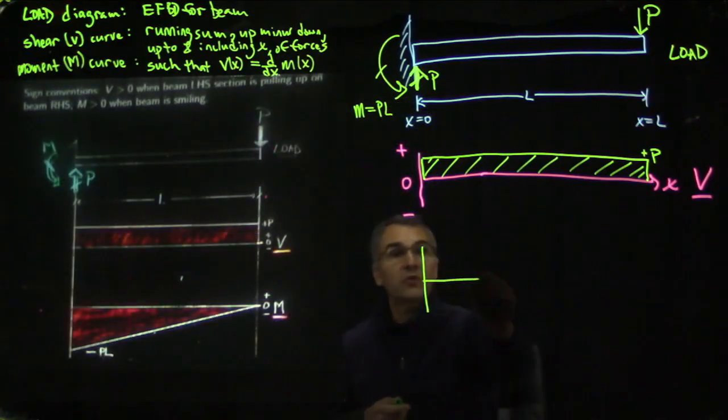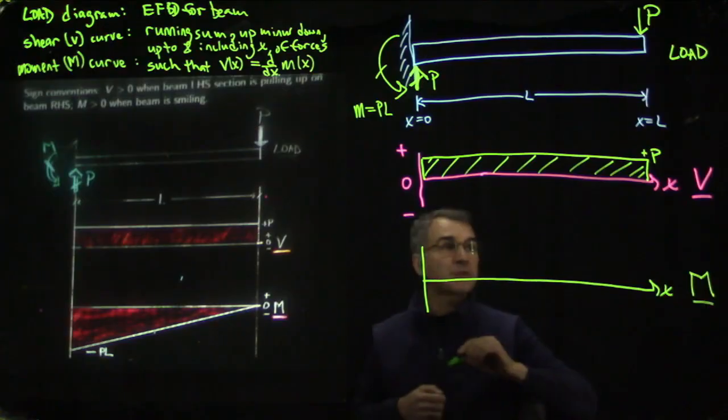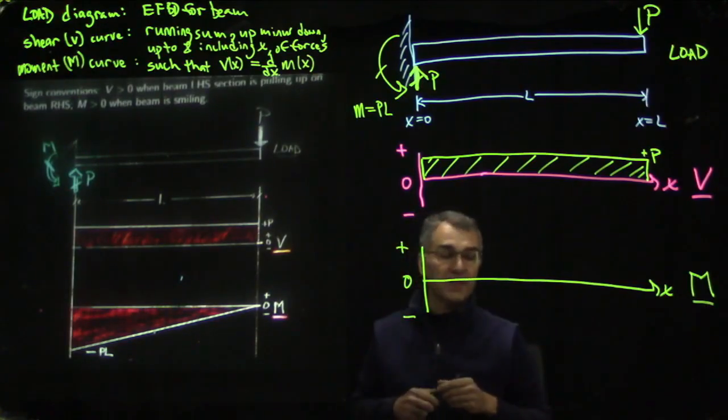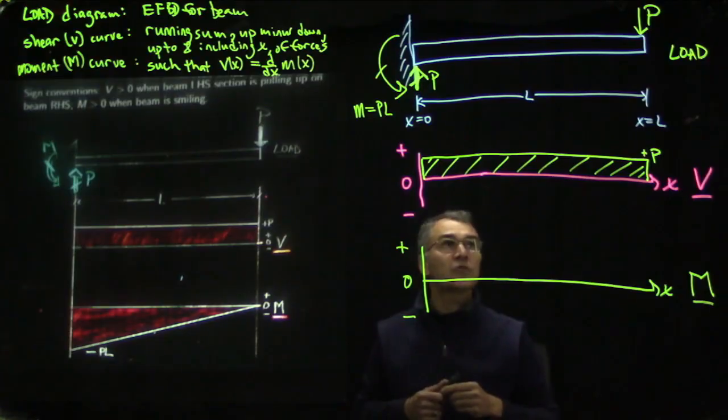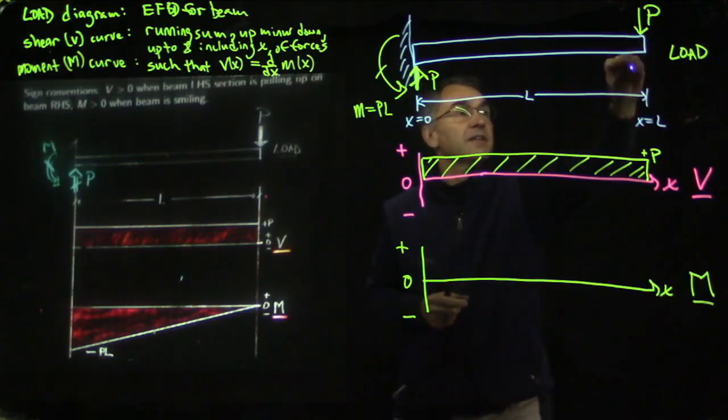Next, we ask, what torque does the left side have to exert on the right side to keep it in equilibrium? And that's this moment diagram, M. So we'll see whether it's positive or negative, but it has kind of a funny sign convention. So first of all, if you go right out to here, then there's basically a negligible torque. It's just this force P, but there's no lever arm. So it's just a negligible torque.